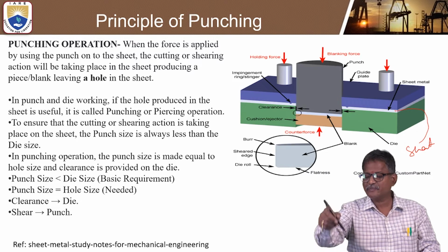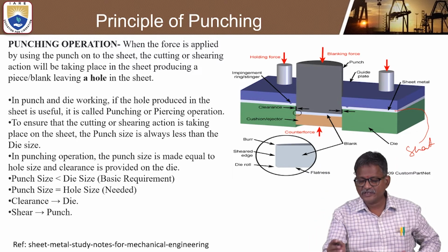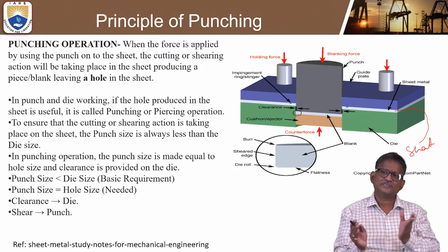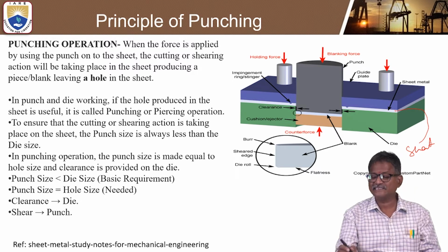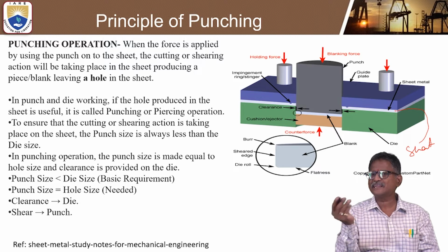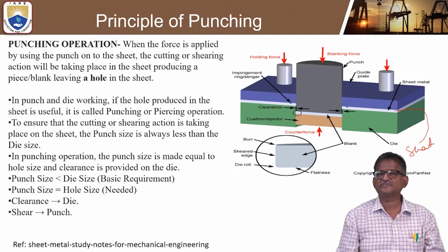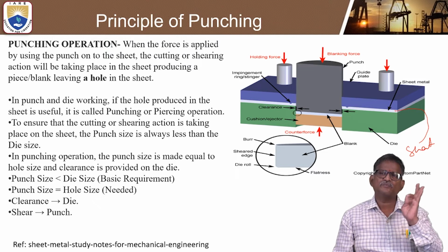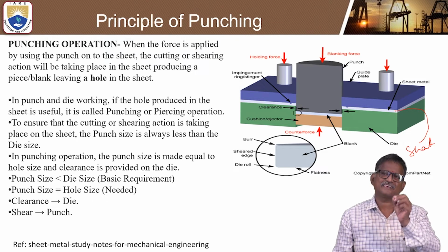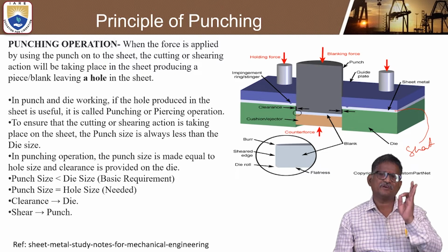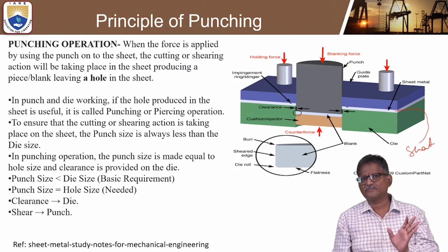And whenever the blanking force is applied, a counter force also acts, so that some clearance may be obtained at the ends. That clearance can be removed by some cutters and some extra machining process also. It will be a negligible amount of clearance, some flash like that will come. Okay, so this is the fundamental principle of the punching process.